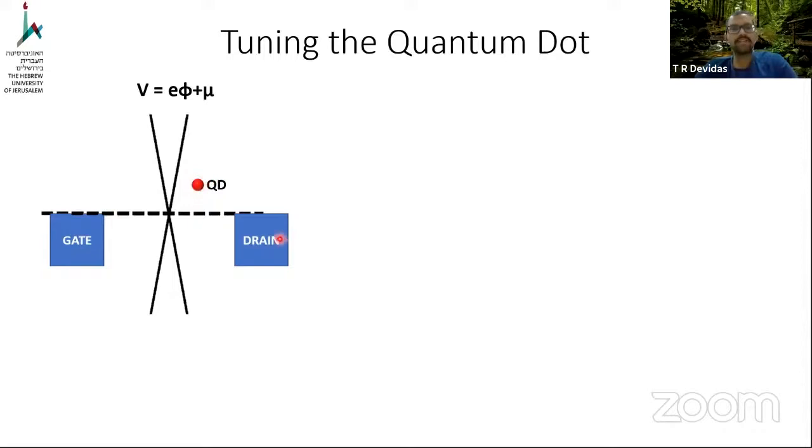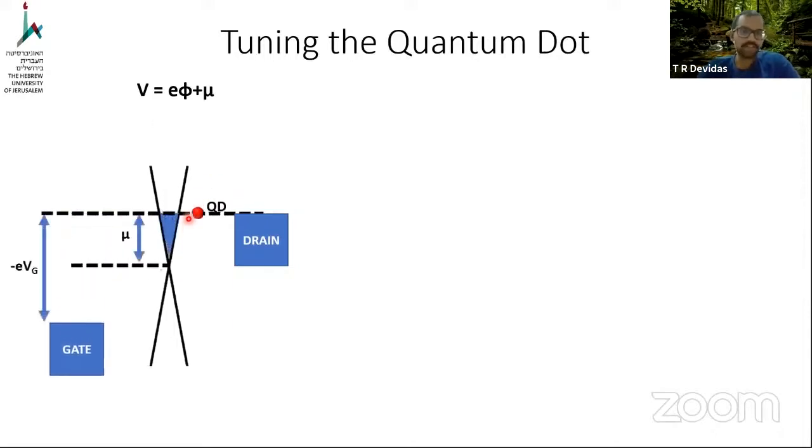When you let the graphene be, graphene's chemical potential is initially at the Dirac point. As you apply a gate and you charge the graphene, the electrochemical potential allows penetration of an electric field, which then shifts the quantum dot's chemical potential, and thus we can tune into the quantum dot's energy states.